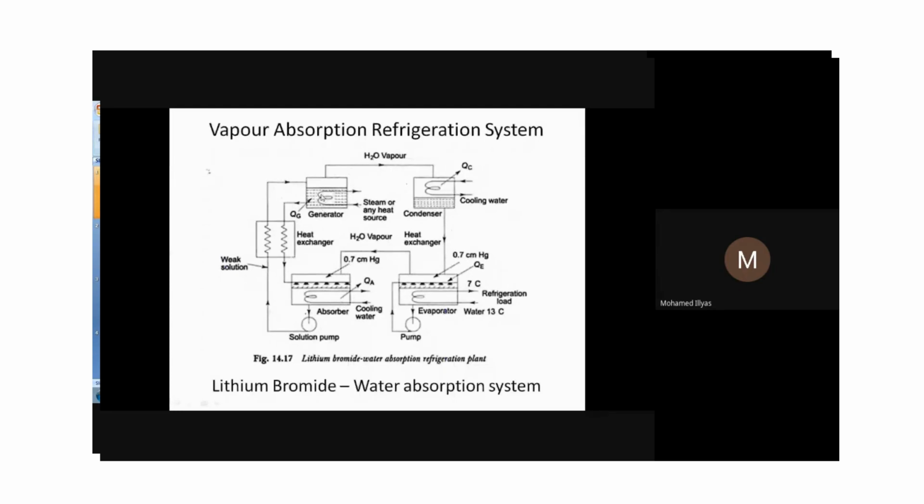So we'll be feeling uncomfortable. Because the humidity is very high, almost 98 or 99%, the evaporation of water from our body during sweating will be very less. So we'll be feeling uncomfortable. That is one point. So at high humidity we are uncomfortable, so we condense the water vapor passing through the condenser here, with some external cooling arrangement.